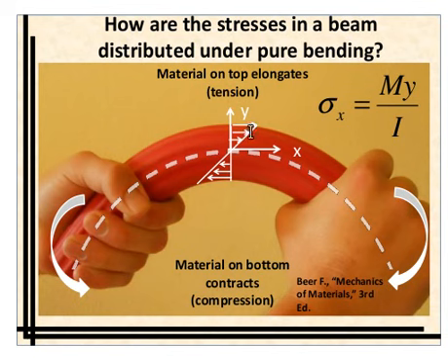So you can see when you're out here at the furthest distance from the neutral axis, this is where the highest stresses occur in tension. And conversely, if you go down the other direction, the opposite surface is where the highest stresses in compression occur.